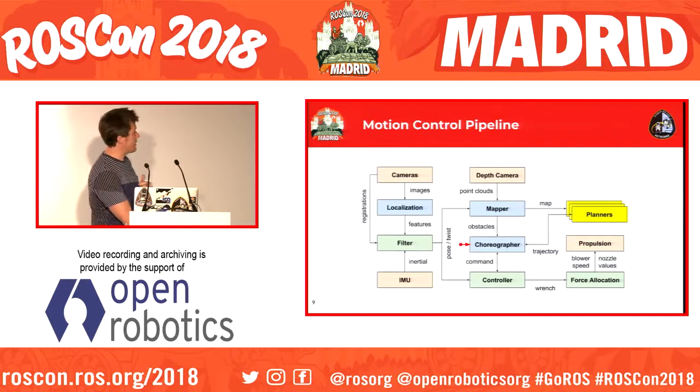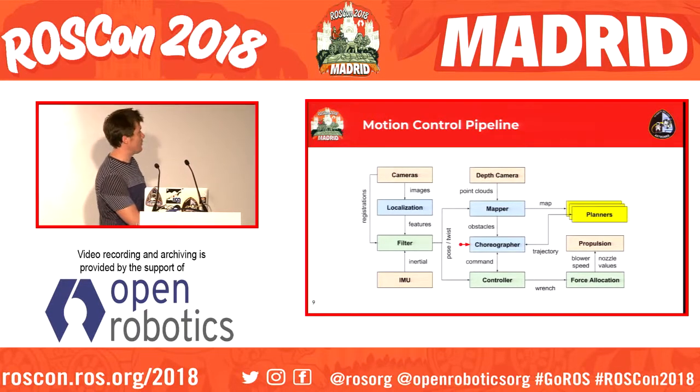Now the controller is, I believe, a relatively simple PID controller. The command would be a segment or a trajectory you want to follow. Then you get the output of your filter, and the controller works out what wrench you want to achieve. So standard sort of control stuff. The filter, which is our state estimator, our guidance navigation system, takes IMU measurements, propagates them forward, and then periodically corrects them with features.